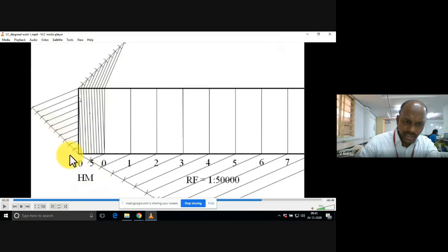We are now dividing this vertical height, right? We have taken already 40 or 50 mm. This height we need to divide into 10 parts. So first you draw one angular line of any angle, right? You set your compass to any radius and cut 10 equal arcs on this particular line. The last arc you need to join to the other end of the height. You can take 40 mm or 50 mm, nothing wrong. If you take 40, somebody will take 50, both will get the same answer. No change.